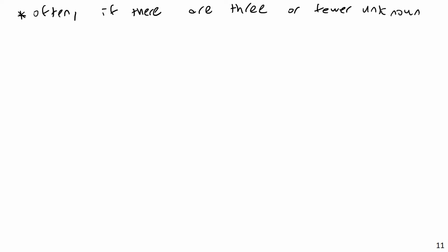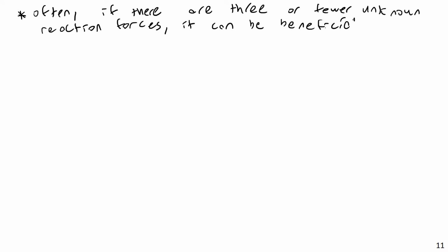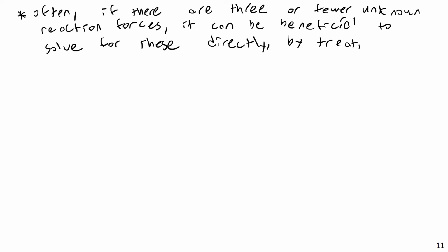Now, I should mention there is one caveat to this. Often, if there are three or fewer unknown external reaction forces, it can be beneficial to solve for these directly by treating the truss as a single rigid body.